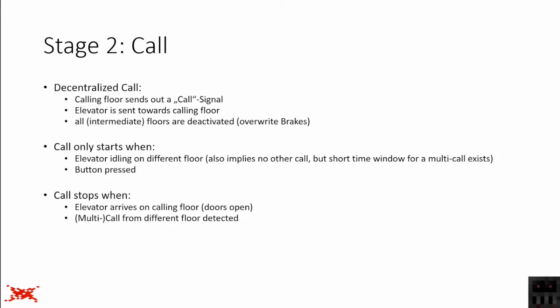The retraction of this signal line, which is usually a negative signal or a zero, a logical zero, is instantaneous over the entire length of the bus. The extension has a delay of 1 tick per module or per step. So I had to figure out what makes the most sense, what edge of a signal can I delay a bit, and what edge makes sense to be as fast as possible.